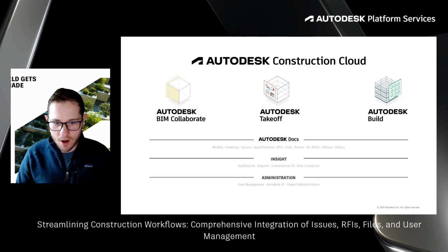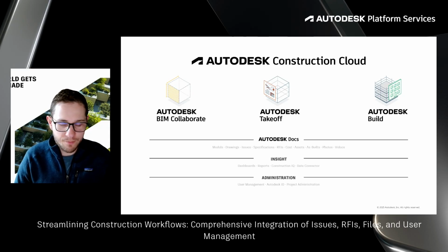You'll see at the bottom Autodesk Docs. So Autodesk Docs underpins all of Autodesk Construction Cloud, meaning those 3D models can move between not only different phases of construction, so planning, designing, pre-construction, construction, operation, and so forth, but all three of our point solutions. So that Revit model, maybe as an example, that's authored in Revit, can be pushed into Autodesk Docs through our cloud share workflow and then used within each one of these three things you see here on the screen.